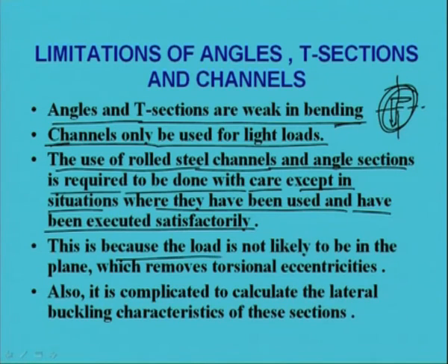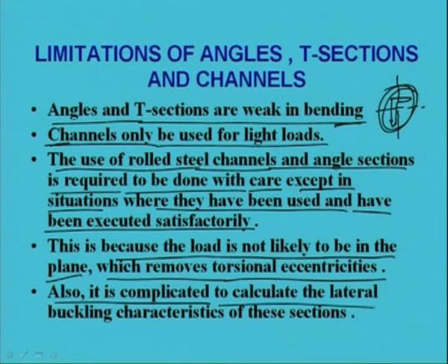Because the load is not likely to be in the plane, so torsional eccentricities may come into the picture, and it is also complicated to calculate the lateral buckling characteristics of this type of section.